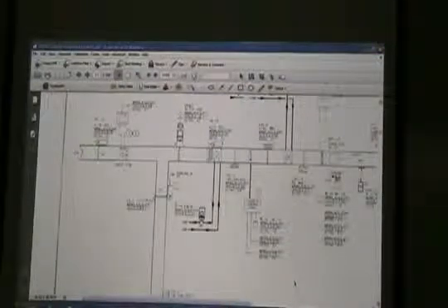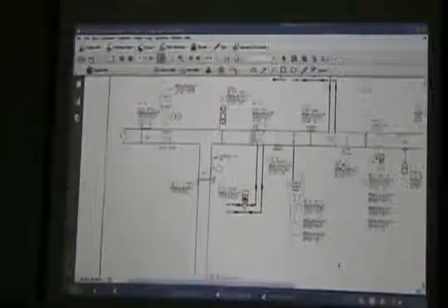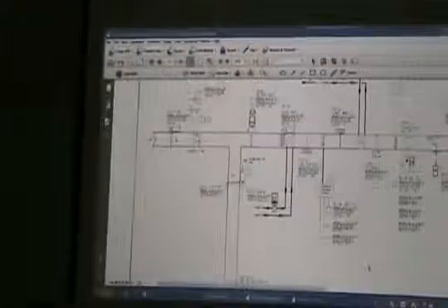The outside air airflow set point should be reset to maintain a positive building pressure sensed by the building pressure sensor. So again, that tells us that he wants to maintain 4,900 CFM, but if the building starts to go negative, then we're going to open that outside air damper even more. The building pressure sensor is common to air unit 2 and 3, so I'm not sure we actually show it on this diagram.